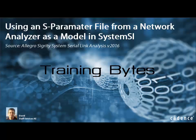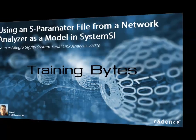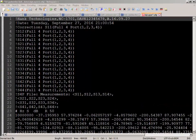Interconnect S parameters can be measured with a network analyzer and saved to a file that can then be used as a simulation model in System SI simulations. Here we have a 4-port S parameter model that was measured from a differential pair transmission line on a network analyzer and saved to the file